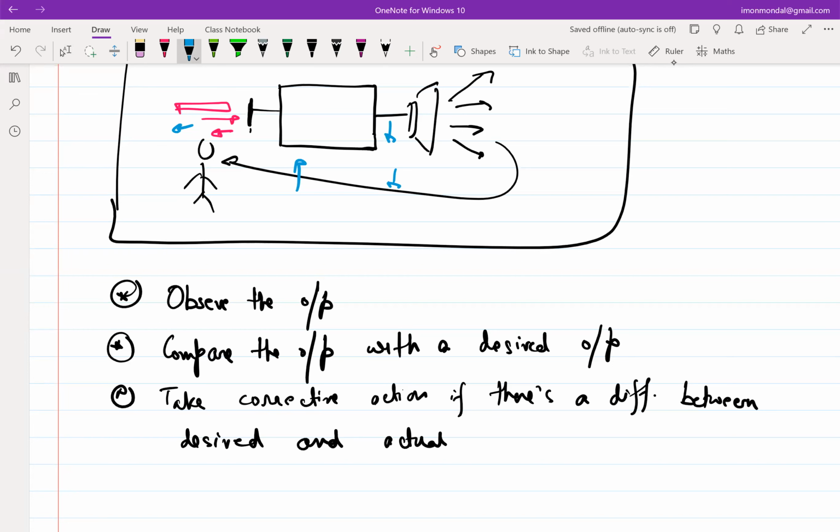So in any system that has feedback, the way to understand whether it's negative feedback or positive feedback is that, once you know the components of the system, you inject a hypothetical excitation in some direction. In this case, I assume that the volume went up. Then I went around the loop and tried to figure out whether the loop action is trying to reduce that injection or increase it. If the sense of the feedback is such that it's trying to reduce the injection, it's a negative feedback loop. If it's trying to increase the injection, then it becomes a positive feedback loop, right?